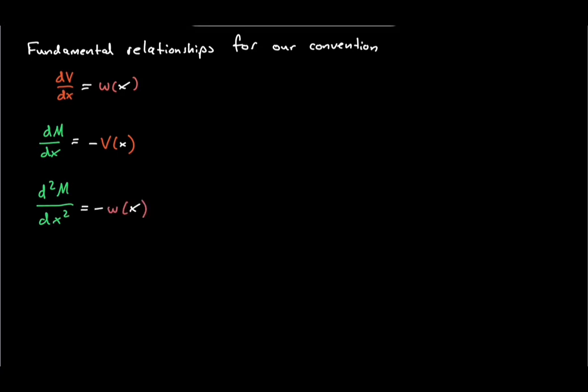The main lesson is that the equivalent force is not just a shortcut. It is the bridge between a continuously distributed load and the equilibrium equations. As the cut moves, the amount of included load changes. That is why the equivalent force, the shear force, and the bending moment all become functions of position.